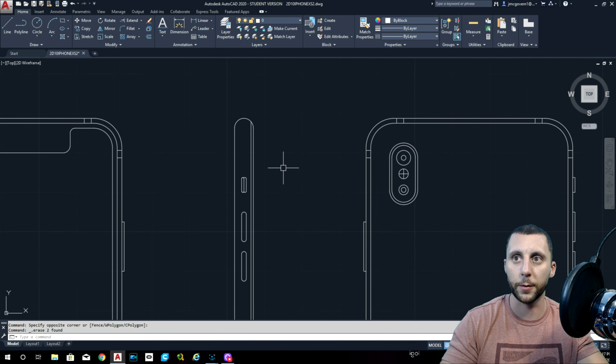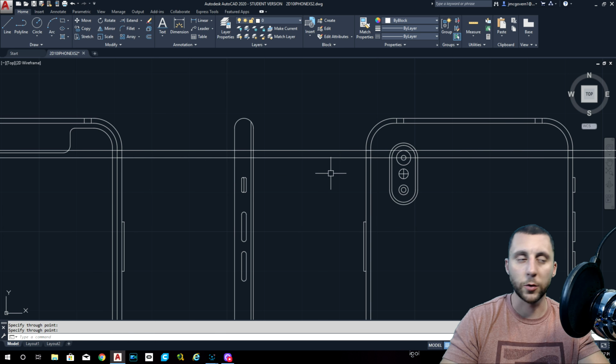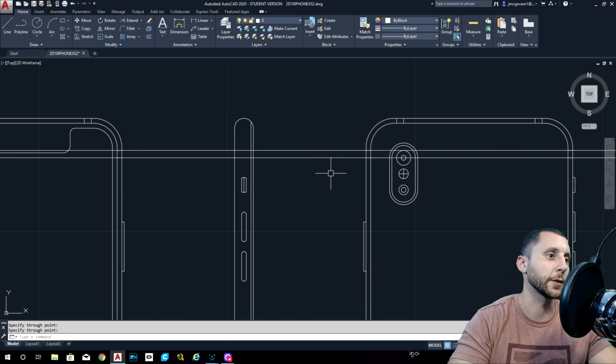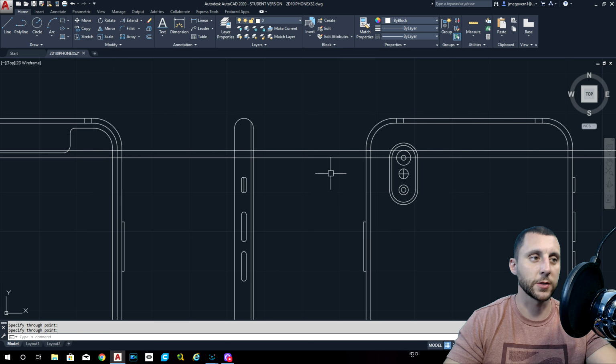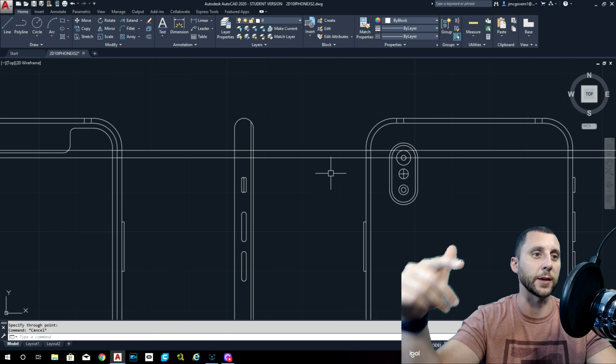Same thing for the top. X line. So by the way, you guys probably hear me clicking a lot when I'm doing that stuff, and I'm not really moving my hands very much. I don't know if you can even see my hands. What I do is, instead of going up and hitting escape to get out of a tool and then hit spacebar to go back into a tool, like if I'm doing fillet radius or something, I actually hit spacebar twice, because spacebar acts as escape and it also acts as enter.